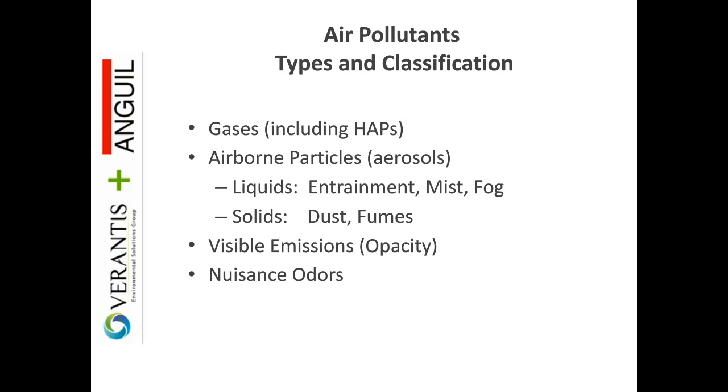So covering the general briefly here, there's actually, at least by definition, a lot of crossover between some of the same types of issues that can be solved using wet scrubbers. In many cases, they can also be solved via thermal oxidation. Everything has its place. So when it comes to wet scrubbing after a thermal oxidizer, we're generally only worried about a few of these, mainly the gases, the HAPs, okay?